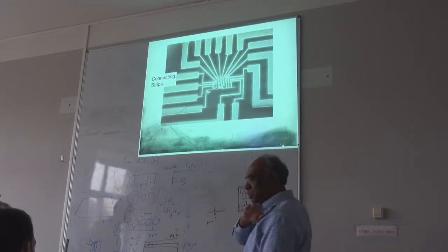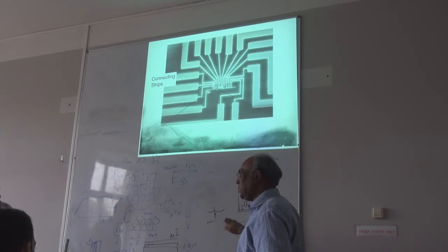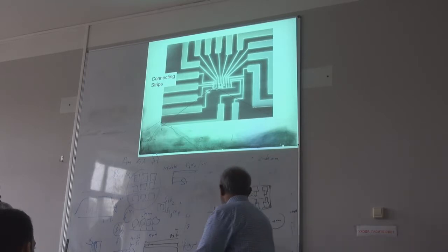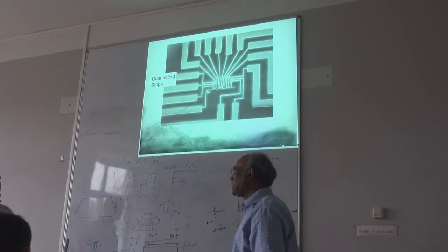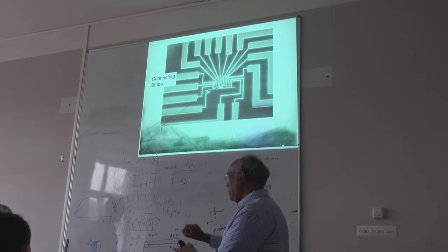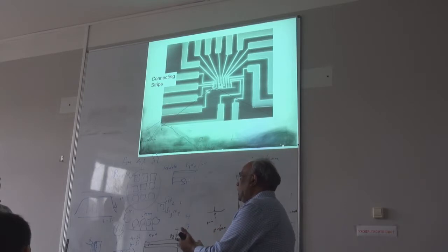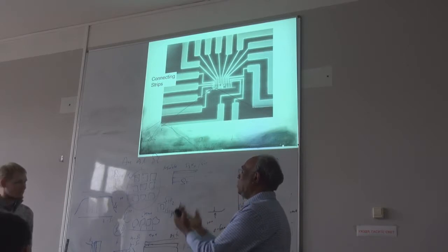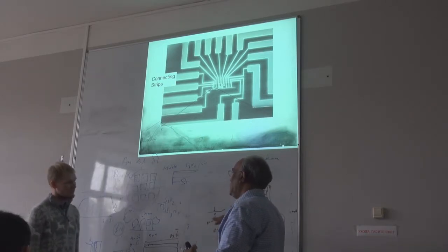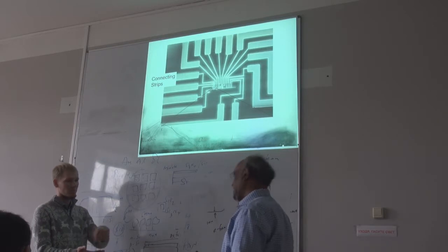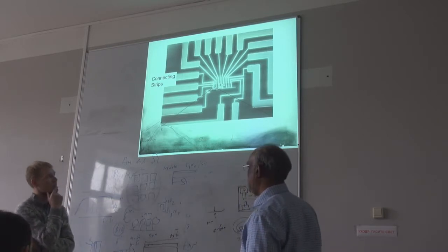So now we put the photoresist, then use e-beam lithography, which is done by using a scanning electron microscope. That's the electron source. You can raster your beam, and at the same time you can do the imaging, so you can view and draw at the same time, writing and viewing both.